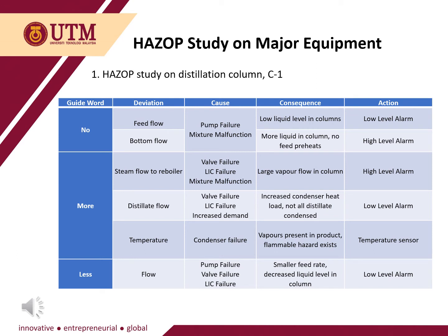Hazard study on major equipment is compulsory because it provides a framework for assessing a whole production plant, one major plant item at a time. This allows potential hazards arising from operation that has deviated from the design point to be found, and a plant profile can be created.